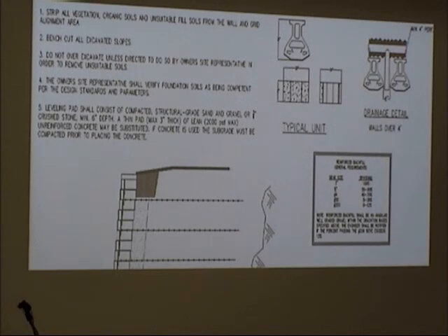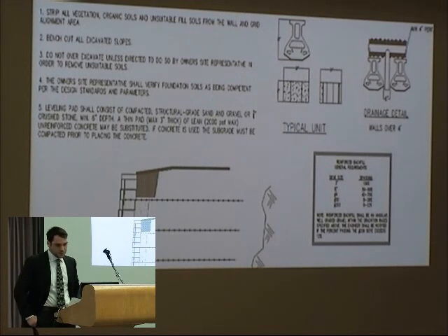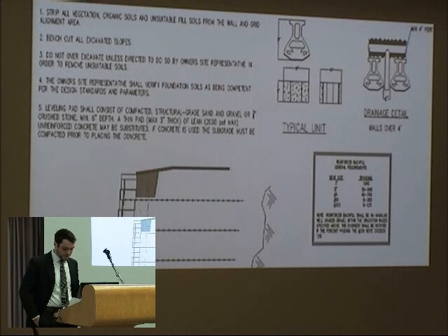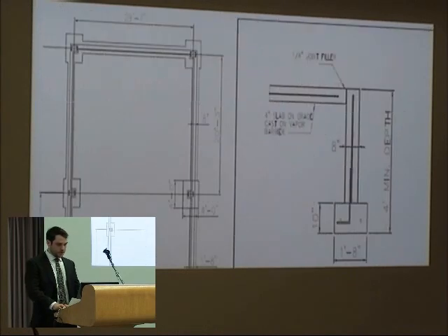For this we used the Stone Terra MSC Wall Systems Engineering Design Manual. Since this was the first time that we had gone about designing something like this, we found that manual to be pretty useful. We decided to go with a StrataGrid 350 geogrid fabric, and in doing our calculations, we checked for the external and internal stability of the wall. For the internal, we checked the pull-out resistance of the geogrid, and we decided to go with uniform lengths for each one of the geogrid layers. Okay, so now I'm going to pass it over to Jason again to discuss foundations.